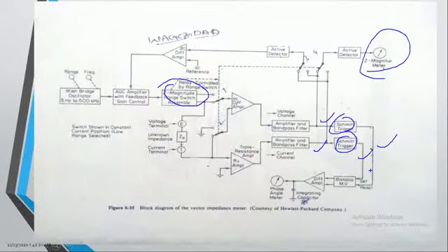So these two are generating the square wave, and we are trying to calculate the phase difference between them using the differential amplifier and the indicator. So, a differential amplifier followed by the integrating capacitor. Based on these components, we can easily calculate the phase difference between the two signals. If the phase difference between the two signals is positive in nature, then I can say that it is an inductor. If the phase difference is negative in nature, then we can comment it as capacitive in nature. The unknown element is a capacitor. So this is all about the constant current mode.